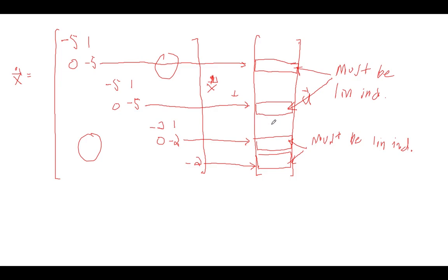Now, what if the answer was this wasn't controllable? If we found that, for example, these two rows weren't linearly independent, what that would mean is you would have to make them linearly independent. And if we assume we can't change the system we already have, so these numbers that are in these rows are set, the way we would make them linearly independent is we would add another input. And we'd have to add an input in the right place.